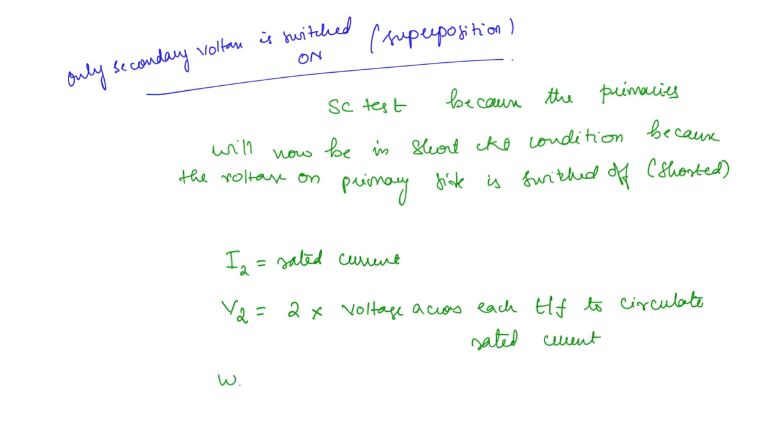And finally, the power is equal to 2 times the full load copper losses of each machine. So you can see that you can get the same results as the OC and SC tests, in addition to the study of temperature rise.